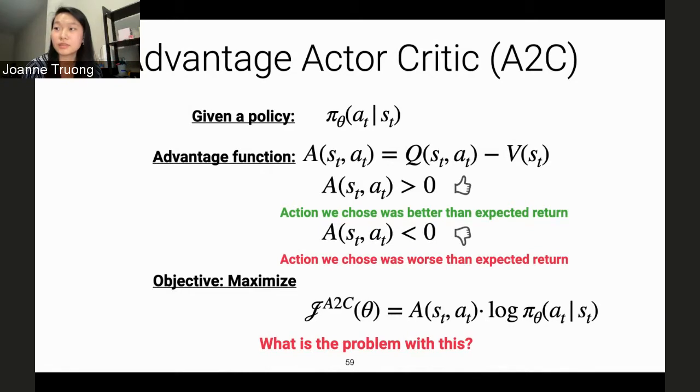The measurements in simulation are actually perfect, so the robot will always be perfectly localized in simulation. The problem is if you want to transfer this to the real world, and I have some examples of this later on in the lecture where I actually did take these policies that were trained in simulation and deployed them on the real world. In the real world, we don't have perfect GPS and compass localization, but we can get pretty close to it using either LiDARs or other tracking cameras to get an estimate for where you are. And these estimates are good enough that they can actually transfer well, even though it was trained in simulation where all the estimates were perfect.